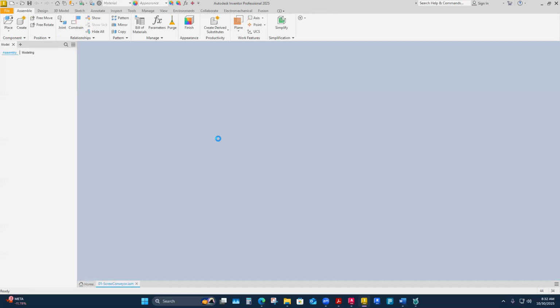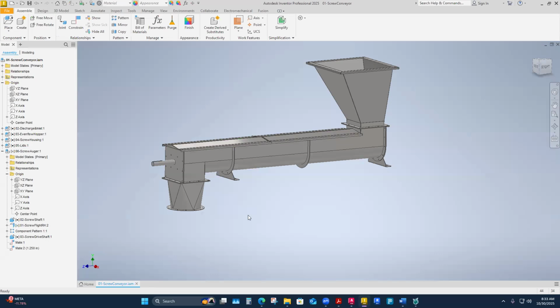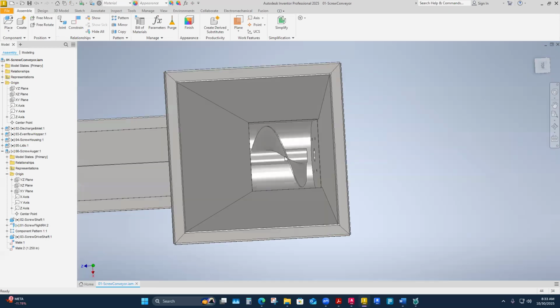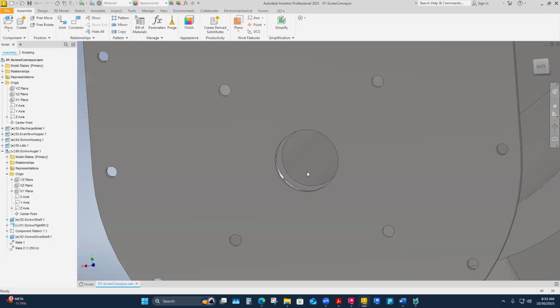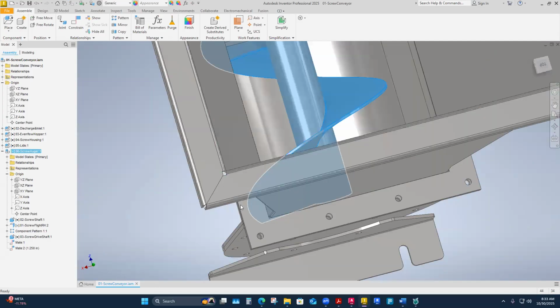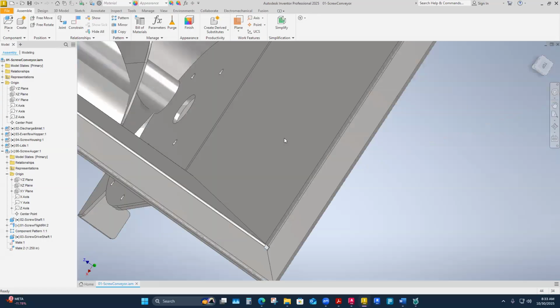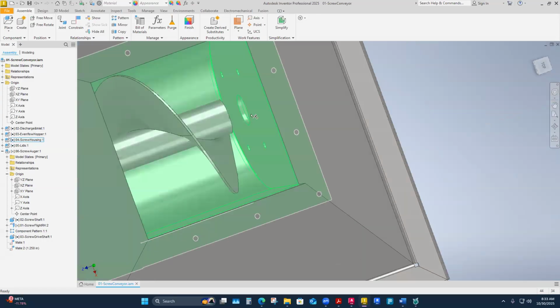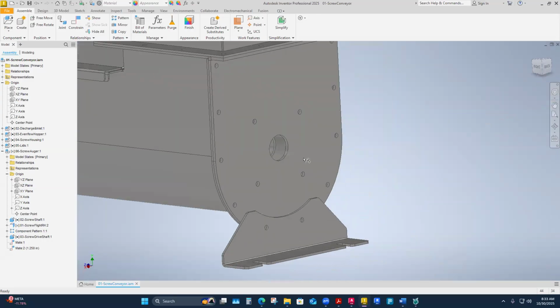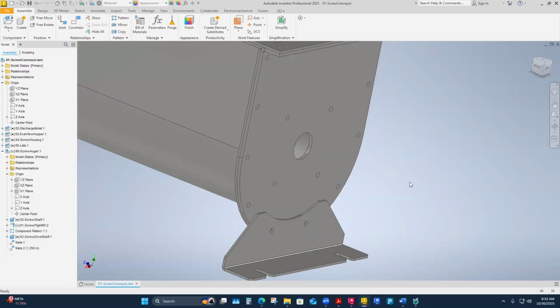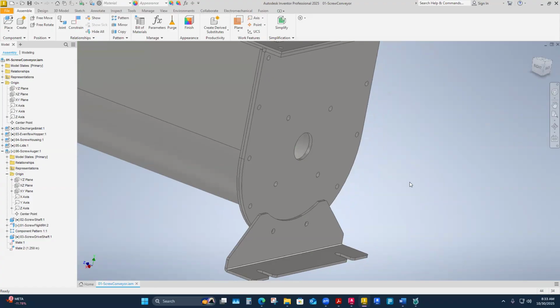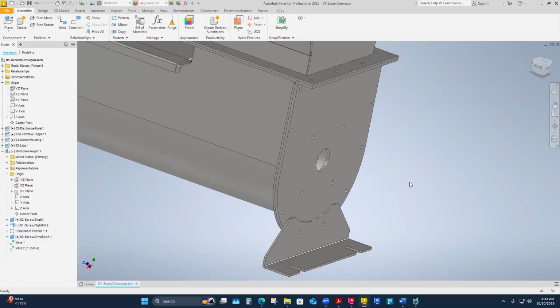Looks like it will. So what I got to do on this thing here, this is an auger. It's in a housing. This thing spins around. I haven't finished the shaft stuff yet here. I've got a piece of pipe in there holding my auger, but eventually I'm going to have a shaft that's going to come out through this end plate here. And then I've got this little hole pattern right here that I'm going to slip a bearing on that's going to hold that shaft in place and allow it to spin.